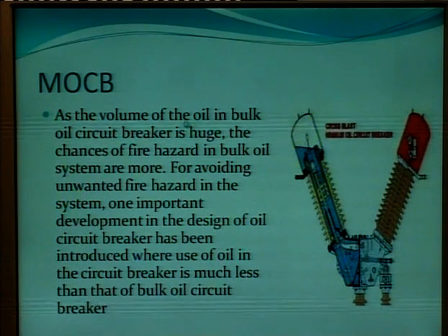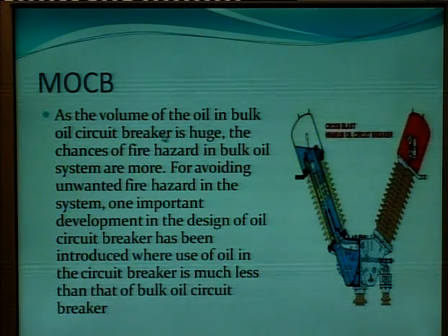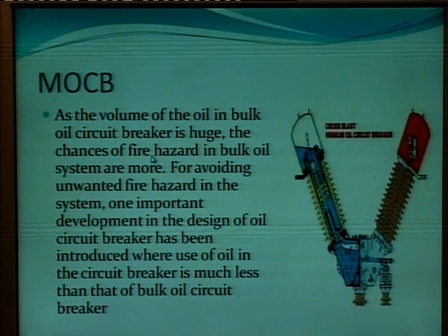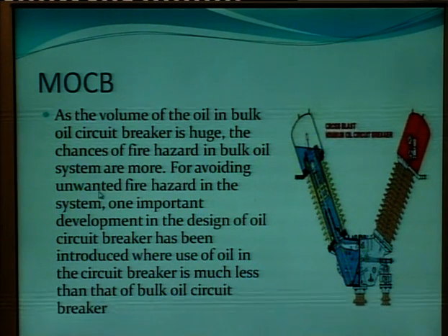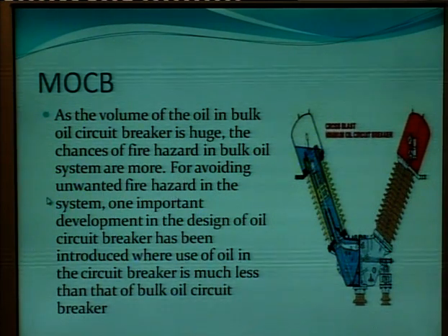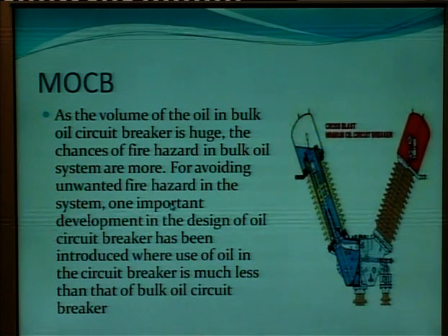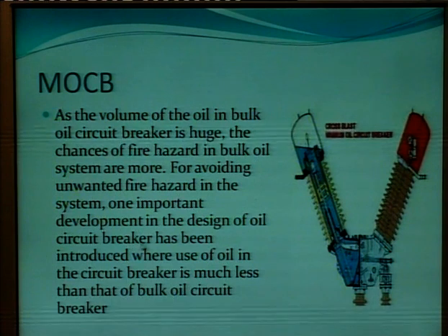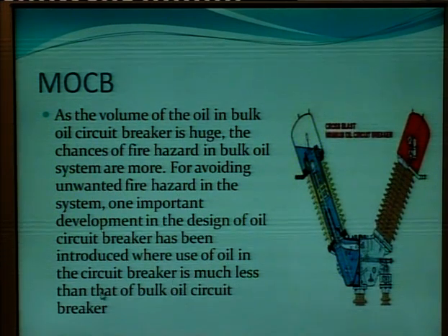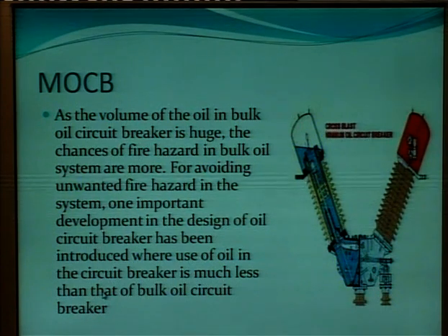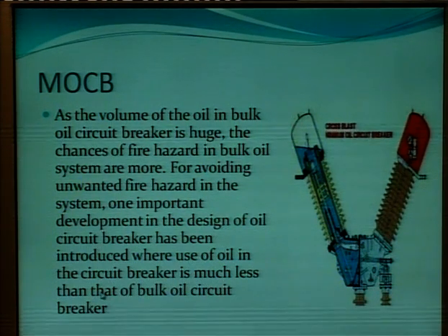So as the volume of the oil in the BOCB is huge, the chances of fire hazard in bulk oil circuit breaker are more. So for avoiding the unwanted fire hazard in the system, one important development in the design of oil circuit breaker is MOCB, in which less oil is used as compared to bulk oil circuit breaker.